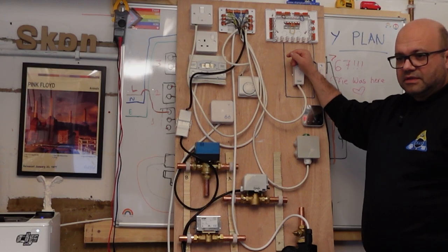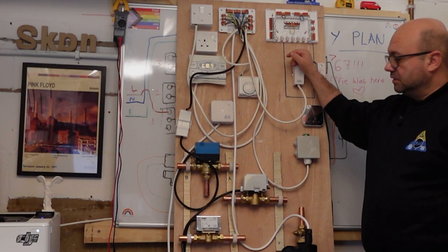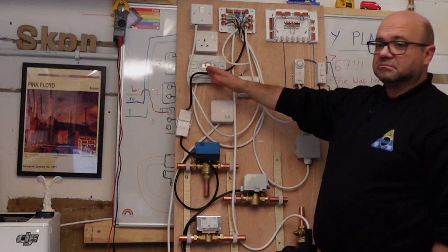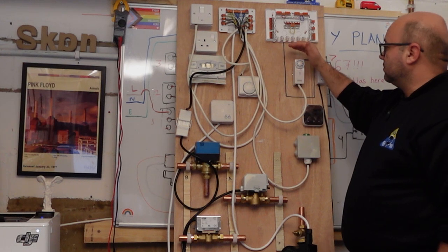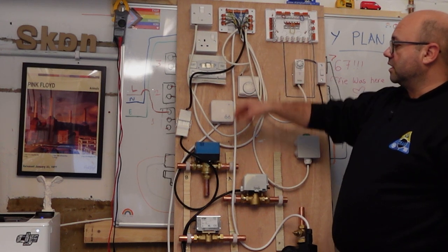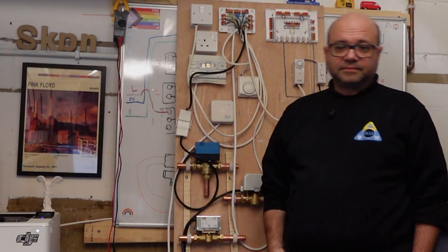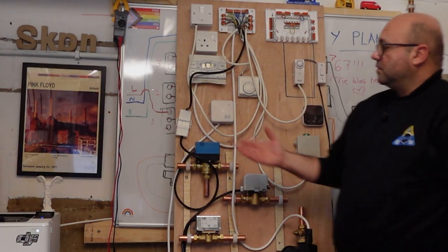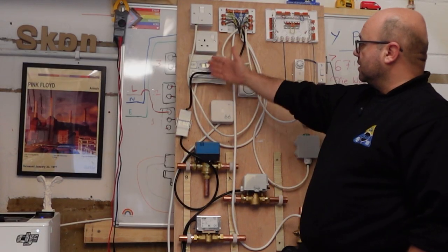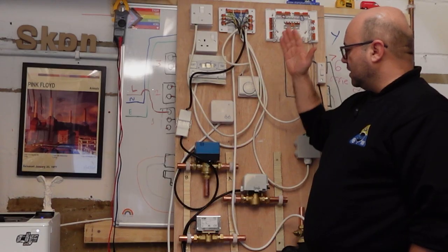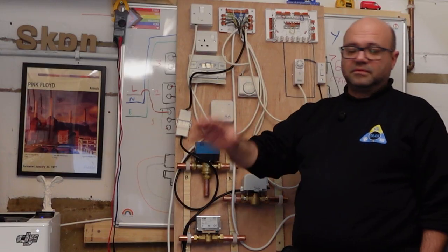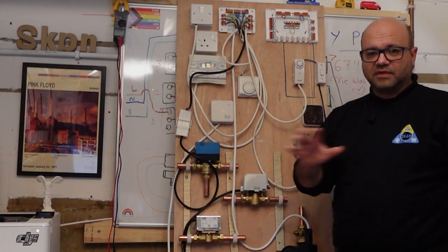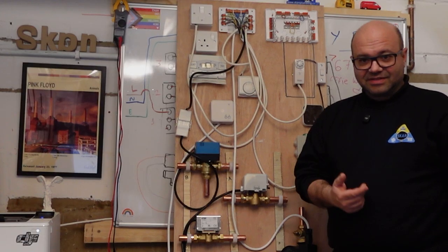In this case, an engineer starts to think about it and says, yes, two things could happen. The timer maybe does not send a good signal, or maybe the thermostat is not working, or maybe the three-port valve, which is absolutely normal because we have to start from the sequence of events. First of all, we send the signal from the timer, then go to the thermostat, and then go to the valve diverter. Before we go to the standard answer, which is, from my experience, the valve diverter, we have to learn at least how to search for the problem.